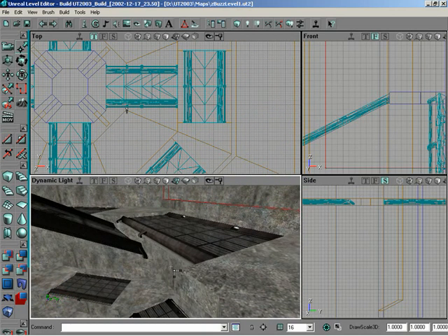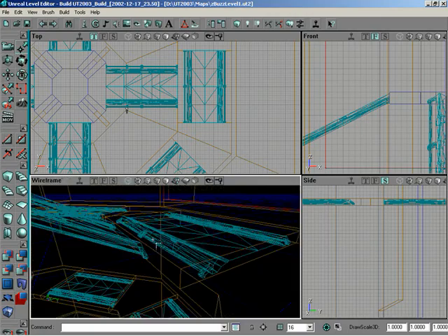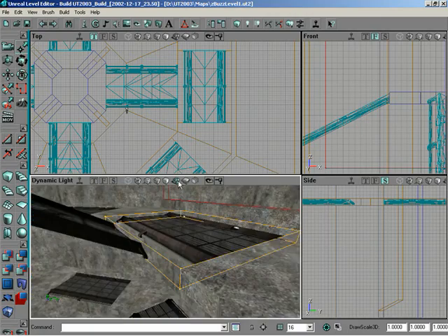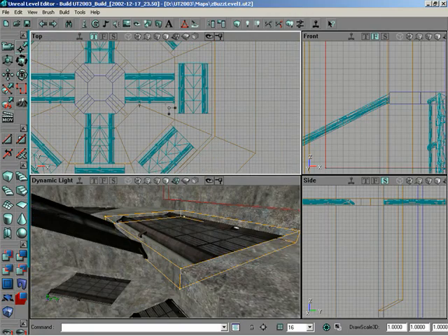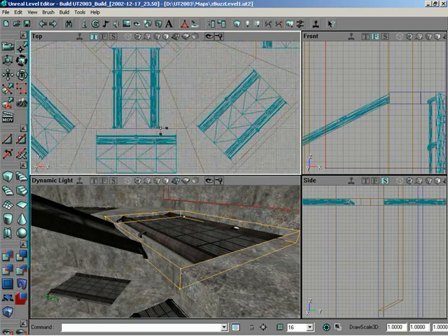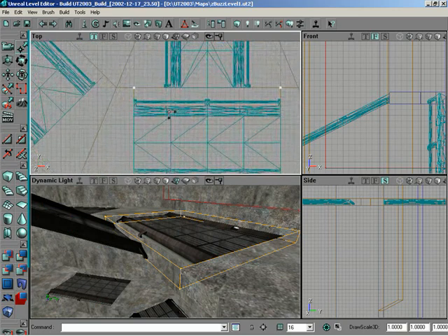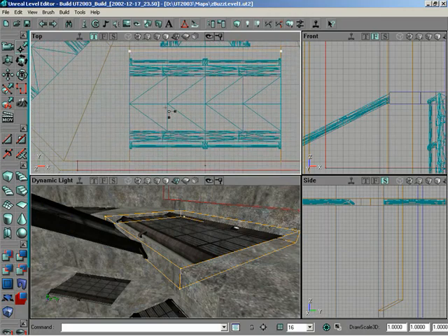So I know that the brush is there, so let me switch over to a perspective wireframe, grab it, go back to shaded so I can see what I'm doing, then maybe go from the top view, still in vertex editing mode, Control-Alt, drag over all four of those vertices, and then pull them back in 16 units. So fast.